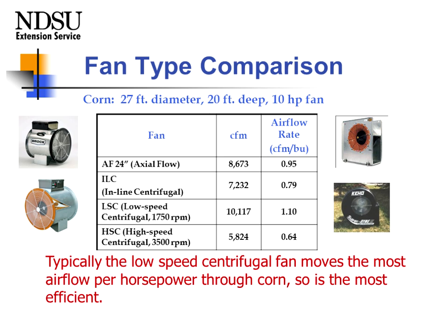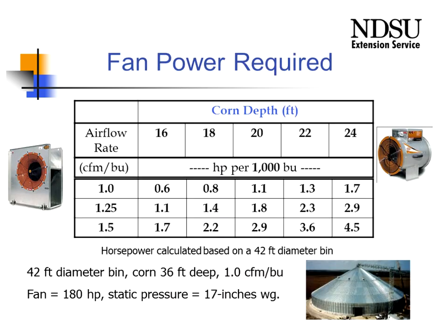If we kept the depth a little bit shallower, the axial flow fan works just fine. The low-speed centrifugal fan gives us the option for those folks that are in regions of the country where you might be doing wheat and corn or crops that have a little more resistance to airflow. The low speed works well on both applications.